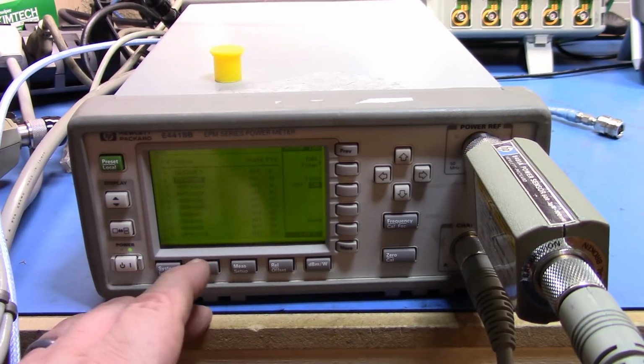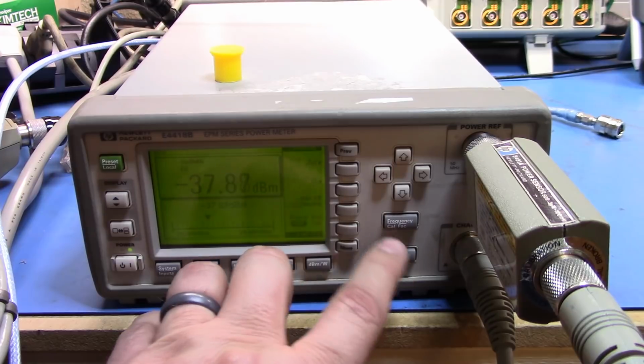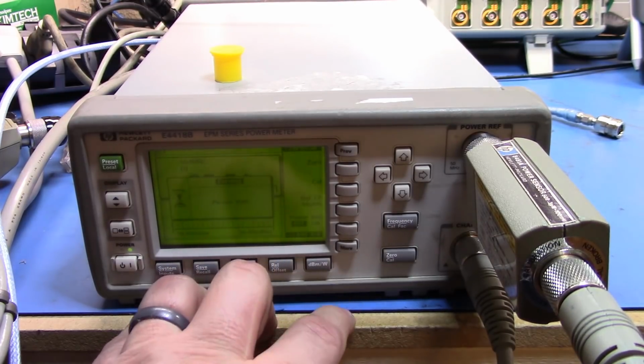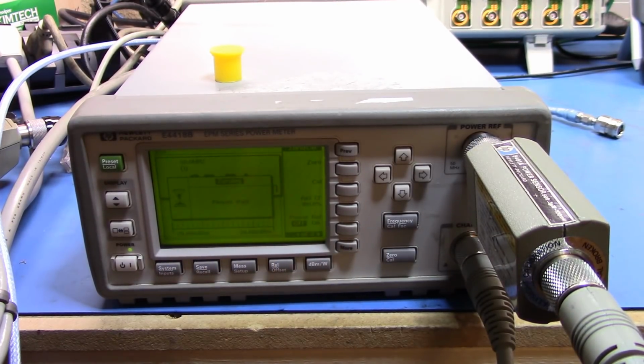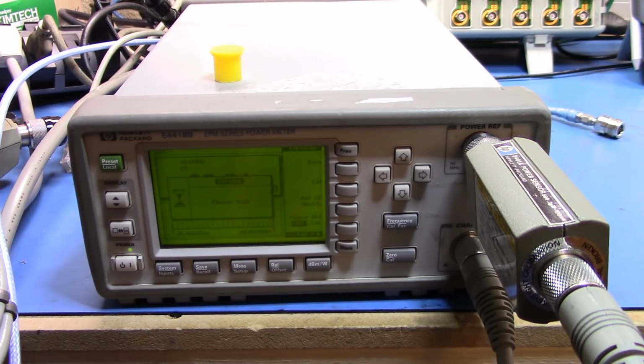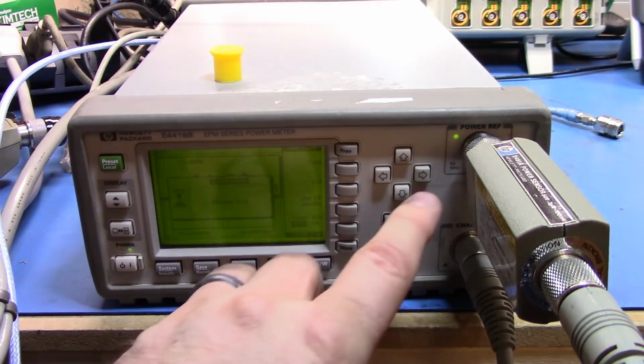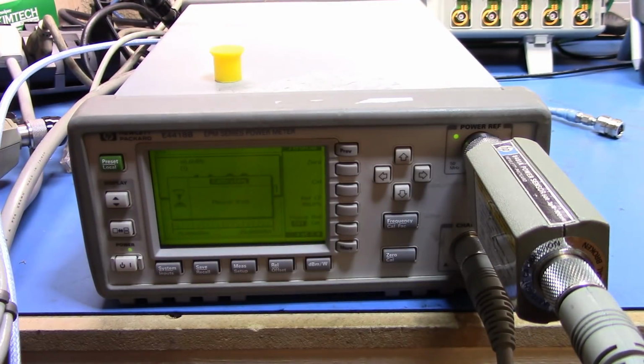I've entered those in. So now that we've got that set, I can come over here and go to 0, and we're just zeroing out the thermocouples. We've got one that will measure the ambient temperature, and one that will measure the RF that's coming in. And so now we can just go in and calibrate that. You can see that the power reference turns on here. And there we go, we're calibrated.